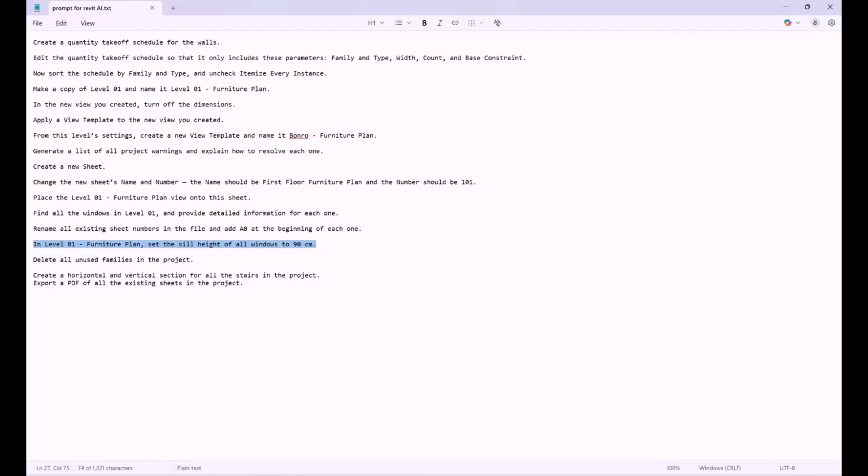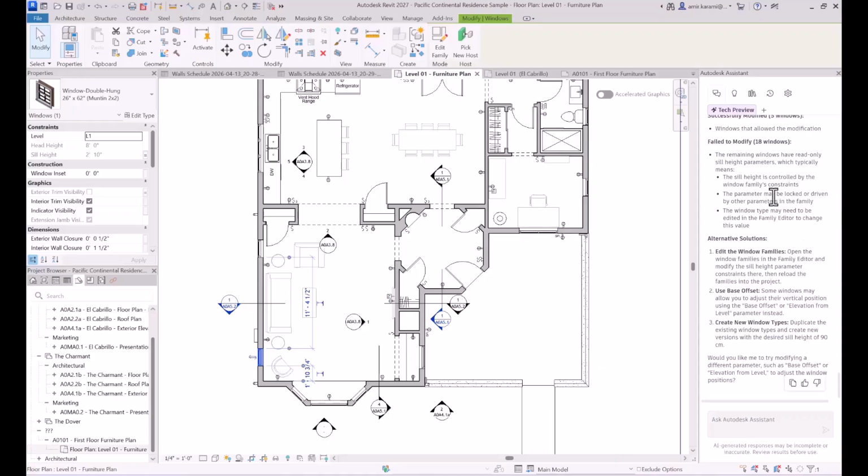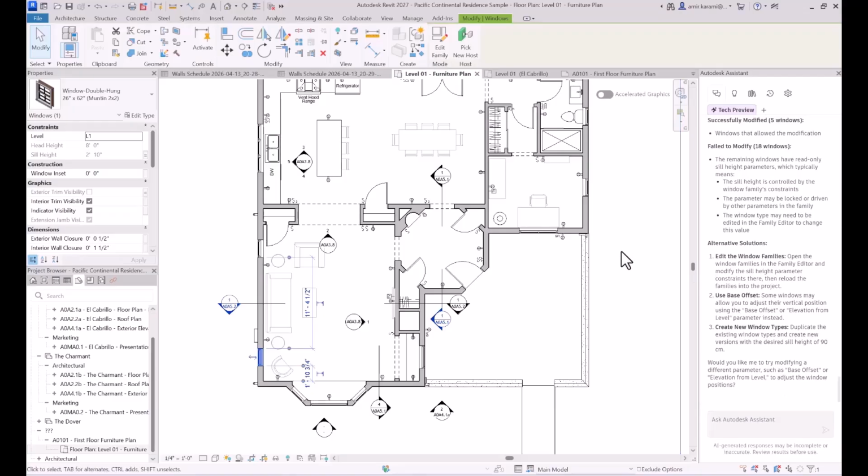Okay guys, let us jump right into our next example. Let's say we got some families within this project that we haven't really used, which is actually very common, by the way. In all projects, there are unused families, some loaded families that are just there and make the files unnecessarily heavy. Families that we would usually get rid of through purging. Now, we want to find out whether this AI could actually help us with such families or not.